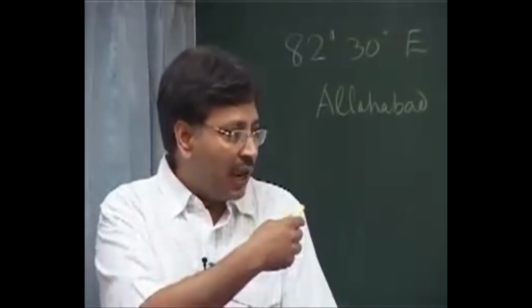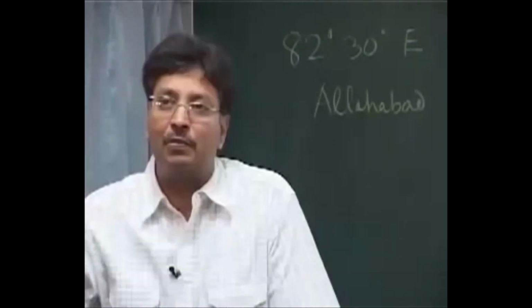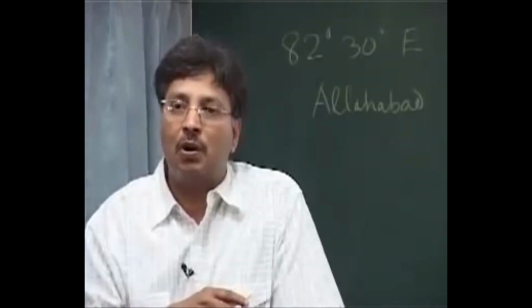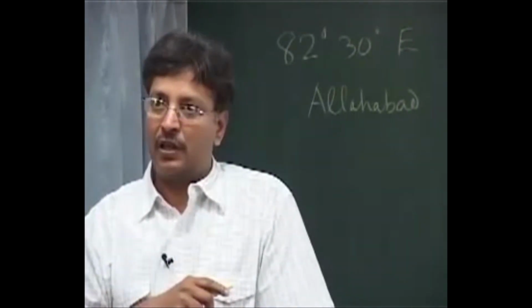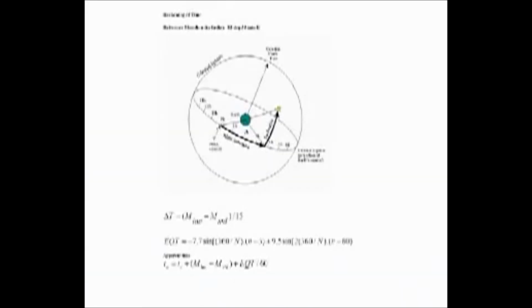But actually the time we see on our watch is all mean, depending on the mean solar position. But we are trying to do a more accurate job. So we have to have something we call the equation of time. The next one I'll show now is the equation of time. It really shows the difference between the mean solar time versus apparent solar time. And what we need is apparent solar time, the time which is existing right now because of the day I am referring to.